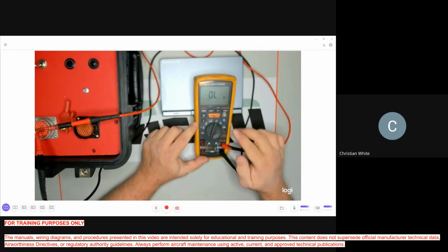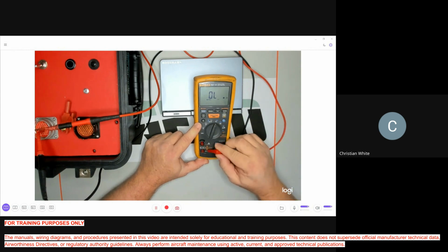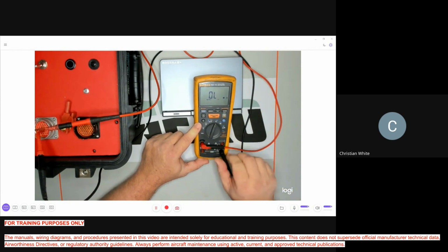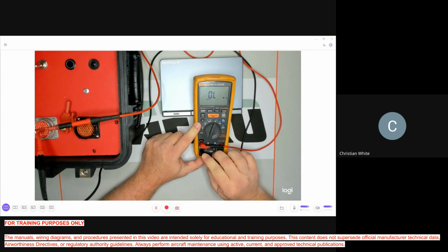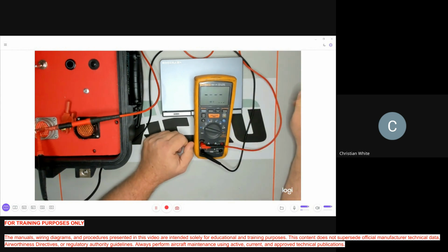Okay. So insulation resistance testing is all done from this side. Your red, it's marked positive and negative. Your red's going to go on the top. Your black's going to go on the bottom. Even though it's colored red, black's going to go on the bottom. And you're going to turn to this section.